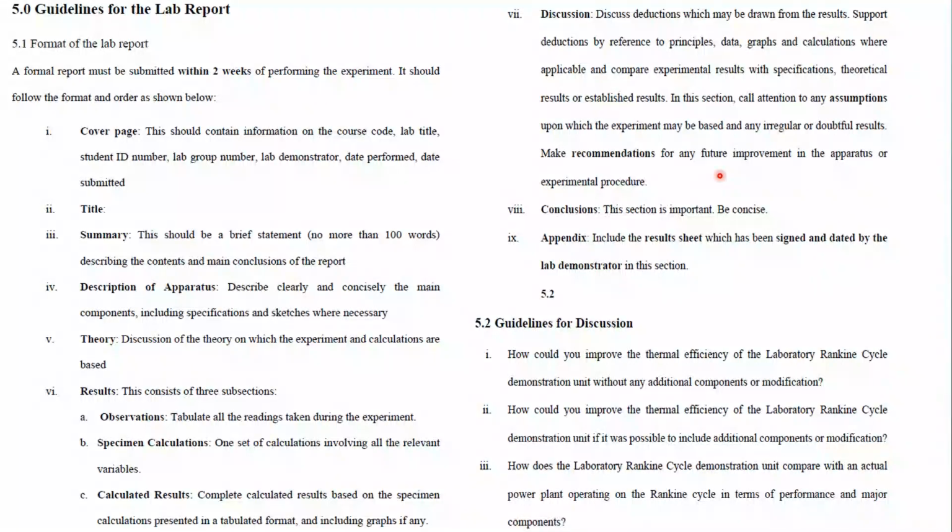Now, these leaks are mainly due to the infrequent servicing of the apparatus. That could affect the normal functioning of each component, and hence reduces the efficiency of the system. So to improve this, you would want to implement a more frequent servicing schedule.